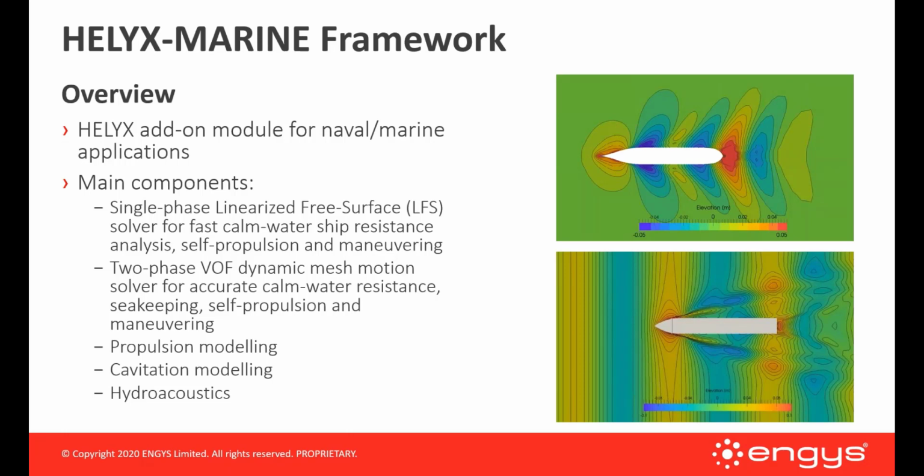Let's talk about HELYX Marine. Well, HELYX Marine is an add-on of our HELYX open source software, which is designed for naval and marine applications, and it consists of different components, starting from a single-phase linearized free surface solver, which is a hybrid RANS and free surface solver, which is designed for several applications, starting from calm water resistance, maneuvering, self-propulsion, and transient simulations.